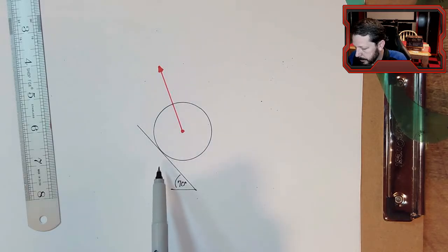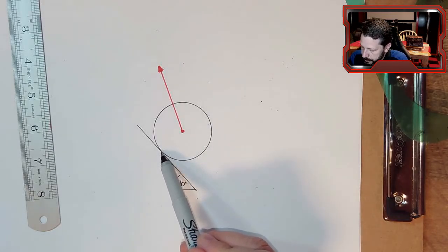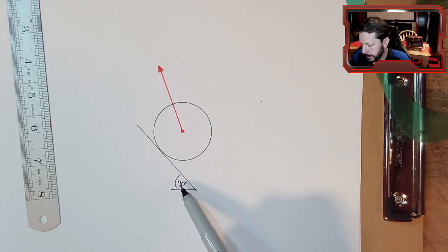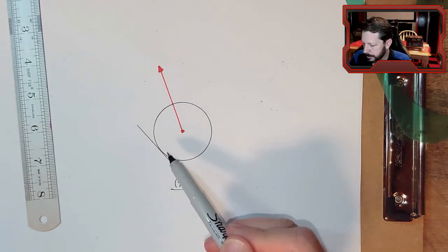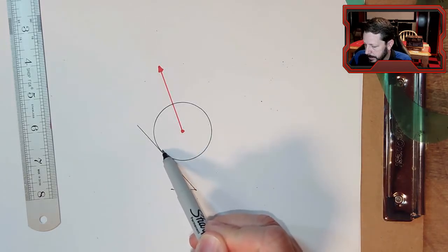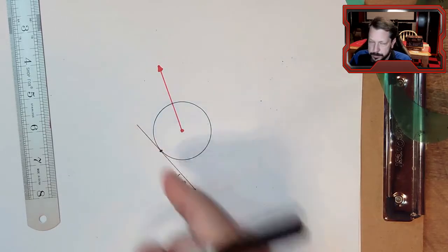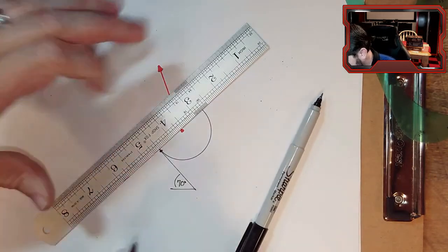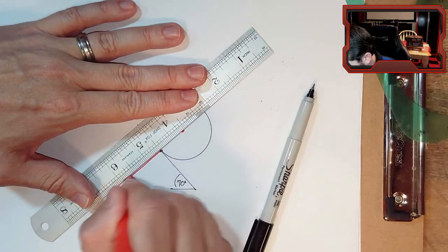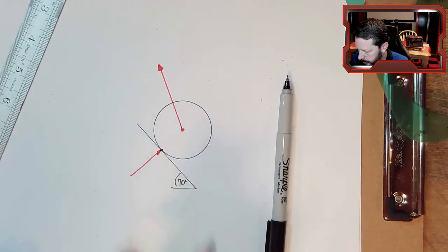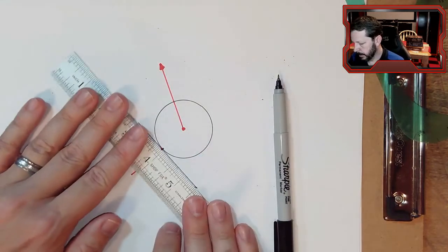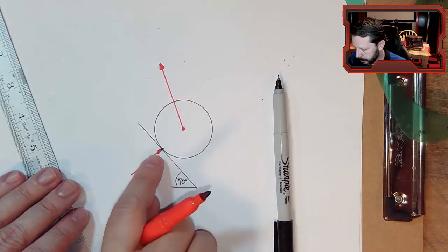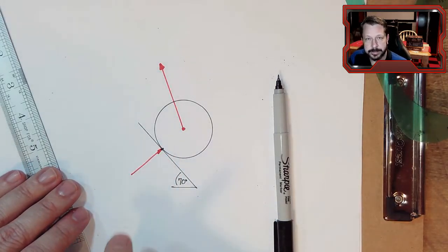What you do is recognize that the reaction force between this barrel and this plane is perpendicular to the plane, or maybe better said, perpendicular to a tangent line at this point of contact, which is also the plane. So they're lined up. We could draw that like this. It is pushing on the barrel. The plane here is holding the barrel up, so it's pushing on it. That would be a compressive force. If it gets large enough, the bottom of this barrel flattens out there, if it's soft enough.